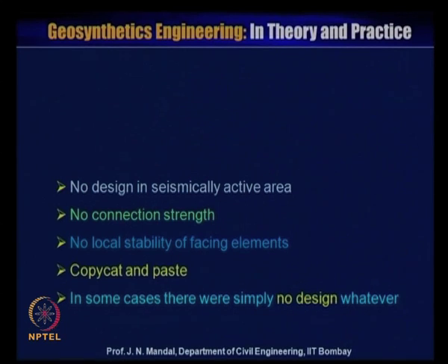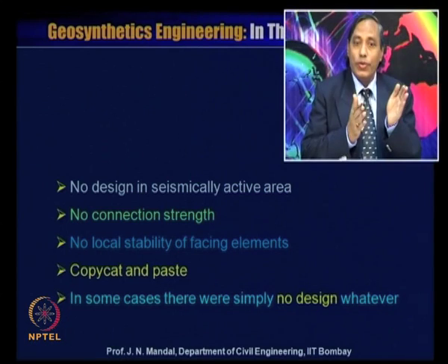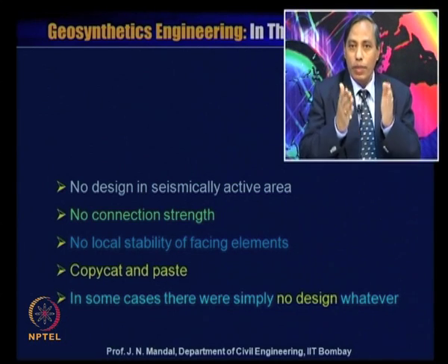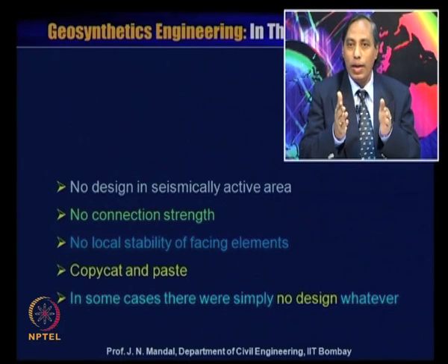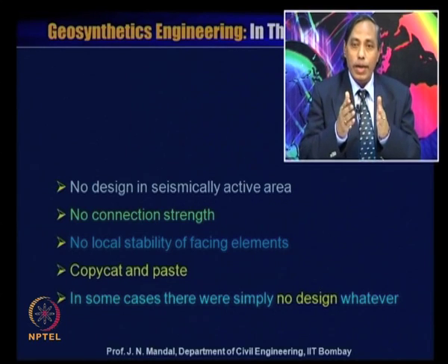Next slide: no design in seismically active areas. Even then, there is a seismically zoned area, so design has not been made. There is no connection strength when you are using a reinforced soil retaining wall. It should be properly connected with the facing element. If it has not been properly connected with the facing element, then the structure may collapse.